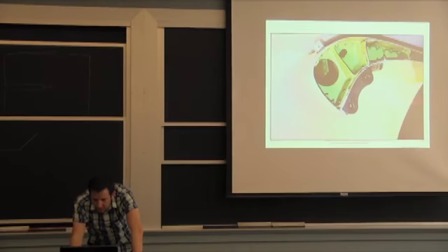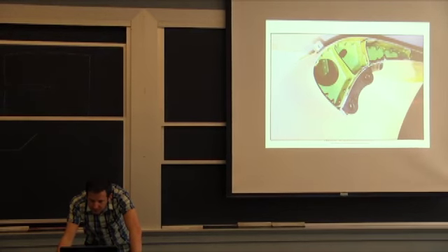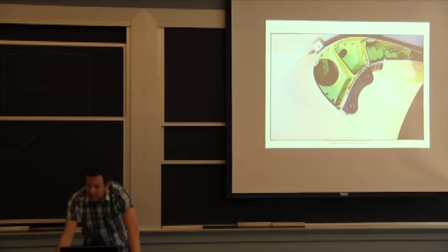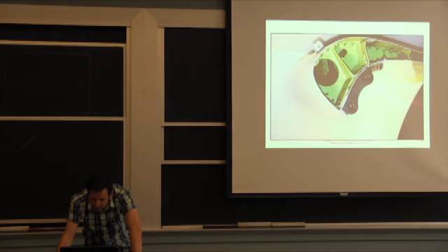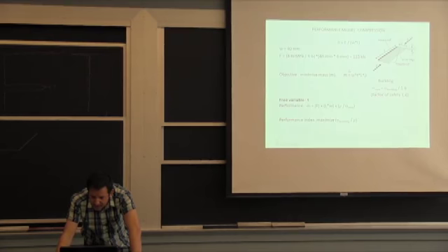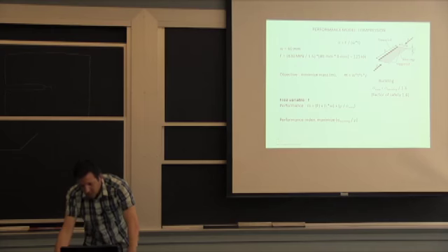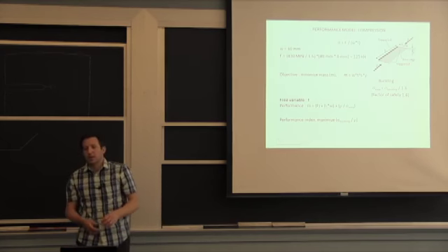Essentially, if you look from this stiffening rib to the next one, what you have is a three-sided supported plate or sheet. And that's what I've been looking at. And same for this one. This rib is supported here on this vertical edge and on top here, and it has one free edge where it can buckle. So the limiting design was this free edge buckling. So it has these very specific equations.